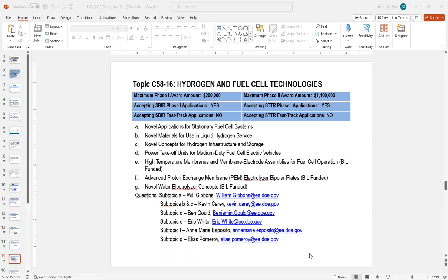Given the broad nature of the subtopic, it might be more helpful to address what is not covered. For this subtopic, systems which don't use electricity to split water into hydrogen and oxygen would be considered non-responsive. Therefore, thermochemical or photochemical water splitting or other systems which don't use electricity to split water are not included in the subtopic. Additionally, the product stream should also not lead to unsafe mixtures of oxygen and hydrogen gas or otherwise create dangerous conditions. A slight mixture might be inevitable, such as the crossover which occurs with PEM or liquid alkaline systems, which is understandable, but the process shouldn't form explosive gas mixtures for obvious safety reasons.